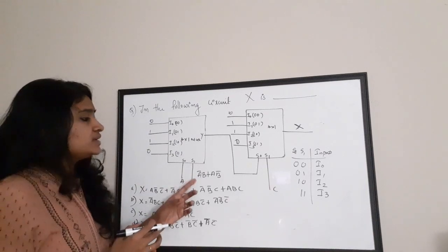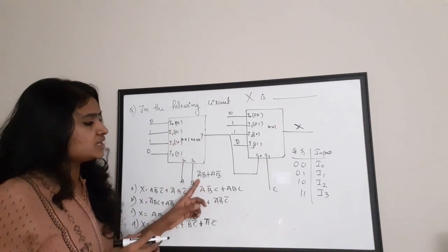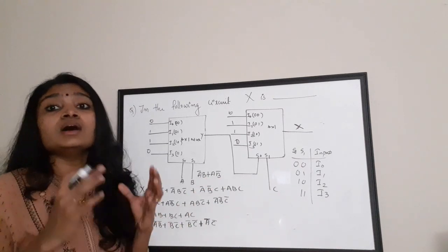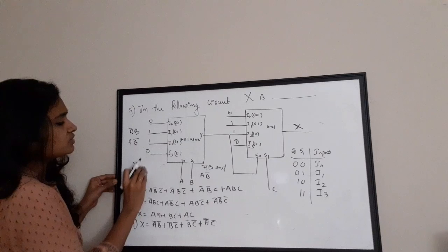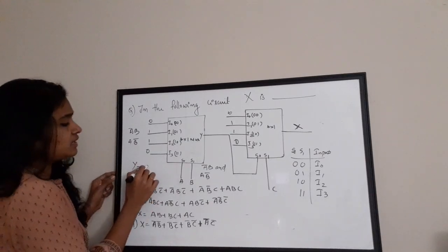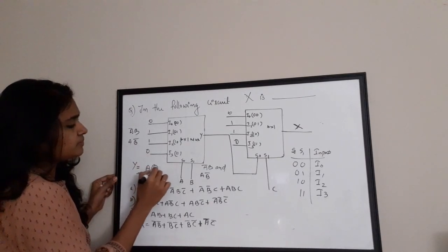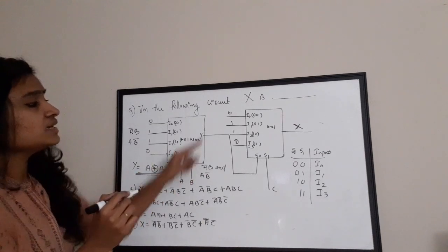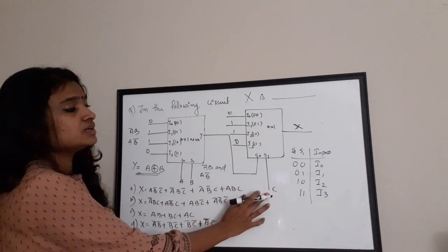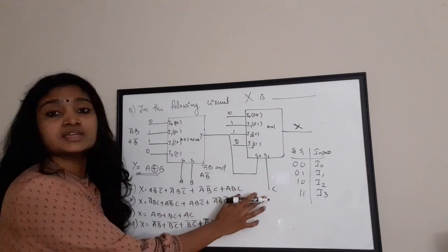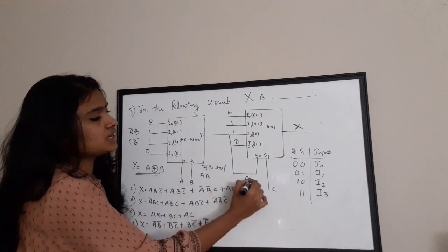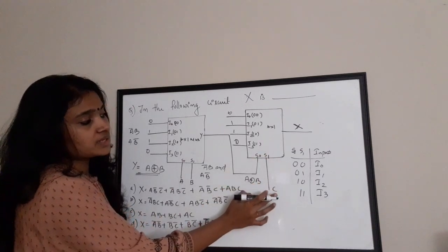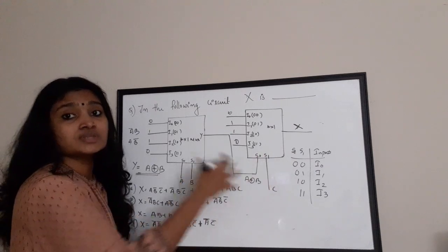Okay. So, what is this expression corresponding to? That is, A bar B plus A B bar is corresponding to what? It is corresponding to a XOR gate, right? So, the Y is A XOR B. Okay, so this A XOR B is given to the select line S0 of your second mux, right? So here it is A XOR B is coming to your second mux. That is a select line of your second mux.